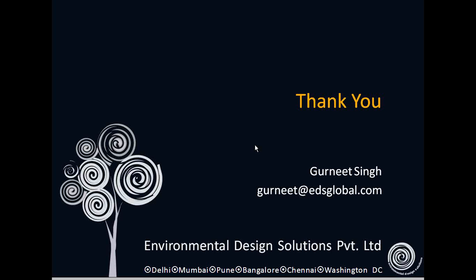Nitin Narang asked the question: do you think LEED and GRIHA projects automatically force integrated design, and is it a way to go for complex buildings? The latest version of LEED and the upcoming version of GRIHA address this issue of integrated design, where you have to show the whole integrated design process, and document that you started from a shoebox model, you have done 3-4 orientations, and based on certain parameters you have finalized this orientation.